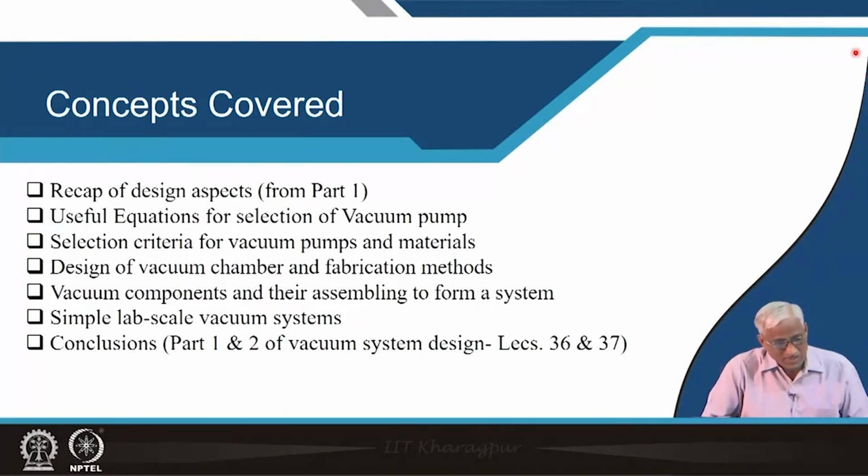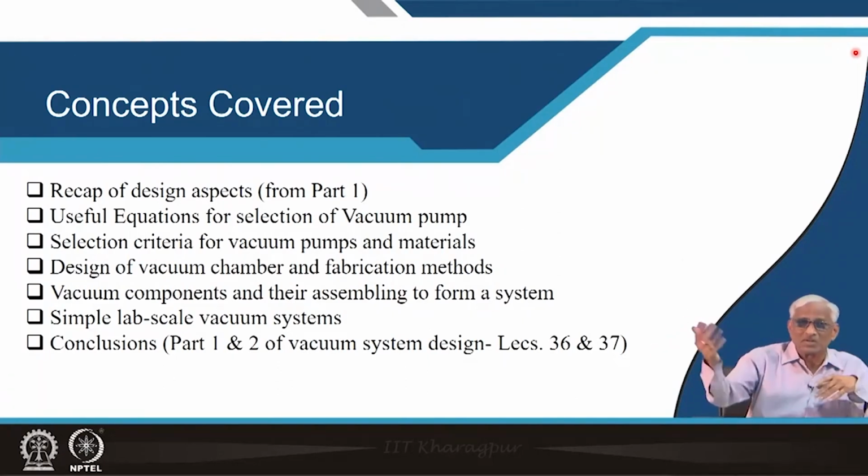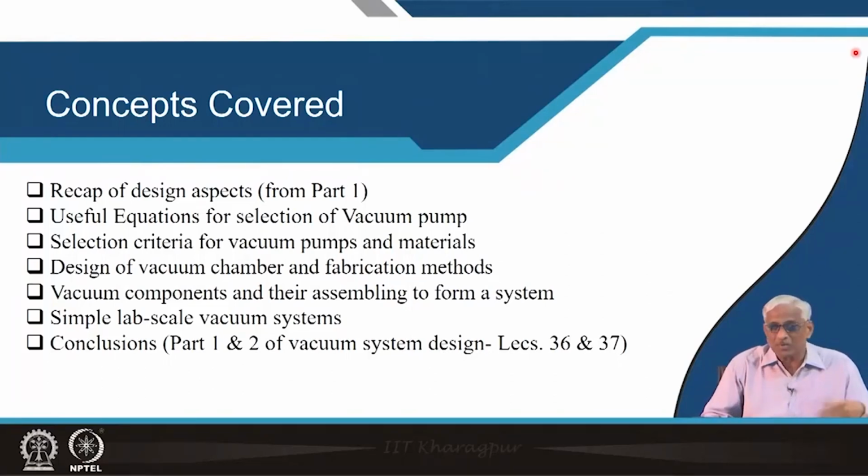So, those design aspects we will see at component level as well as chamber level, including fabrication aspects as per your design. You cannot leave fabrication aspects to some mechanic, you have to tell as a part of your design. Okay. Whether it is brazing or welding, you have to design. If you say, okay, you connect somehow, they will put some adhesive and you will not get even 10 power minus 5 torr, when the system is supposed to get 10 power minus 8 torr, though the pump is good, the chamber is good. So, you have to also keep track of fabrication issues.